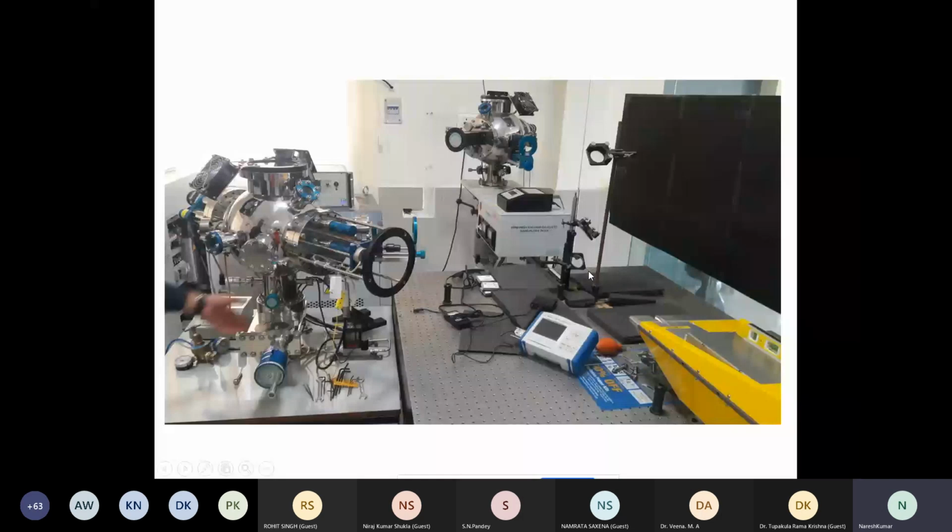Mirrors are very important. Now, when the beam goes inside the chamber, as I said earlier, we need to focus this laser beam, and for focusing the laser beam, we need to use a lens. That lens is not an ordinary lens once again, right? So we would be using a fused silica lens, quartz lens, right? So again, one has to be very careful about these optics, right?